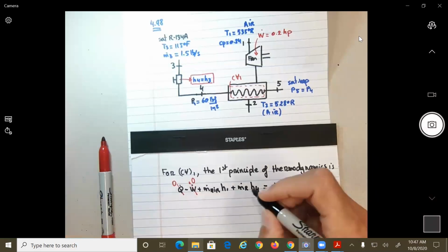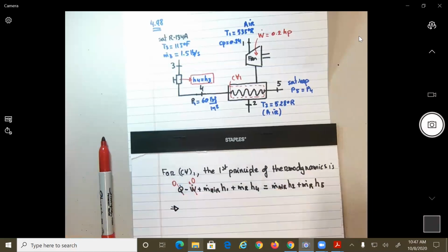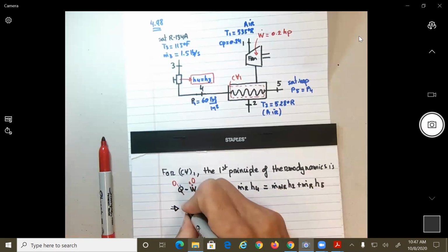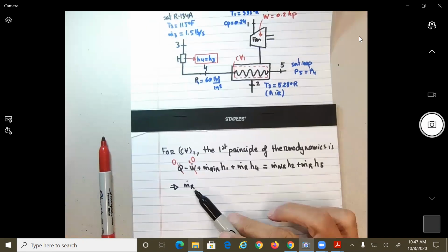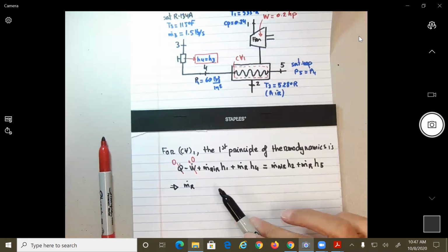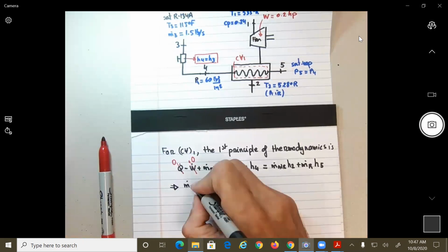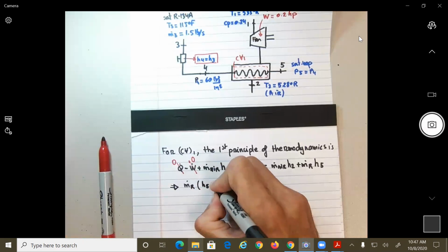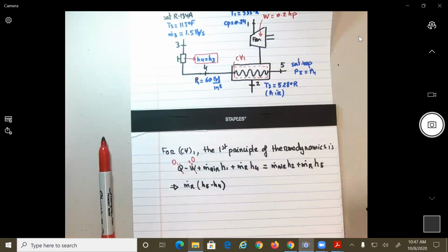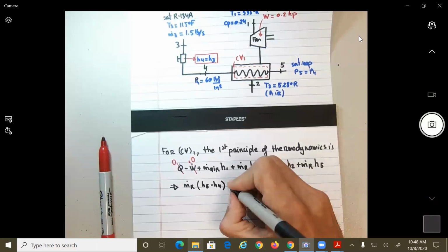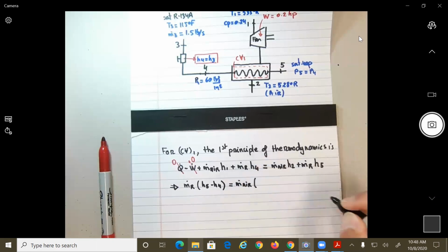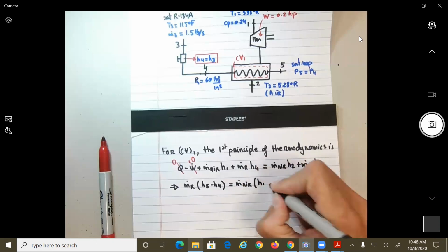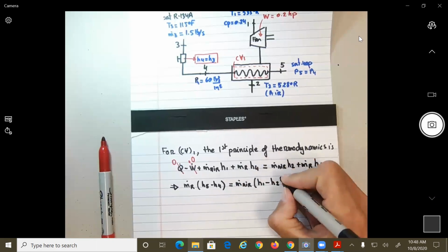We can write that, so be careful here, I'm going to write something that might not be 100% clear, but I hope it's going to be. So let's factor out on one side the ones of the refrigerant. So let's say we move the refrigerant to the right. So we'll have what? m dot refrigerant, h5 minus h4. I move them to the other side. I'm going to move the ones of the air to the left-hand side. So we'll have what? h1 minus h2.